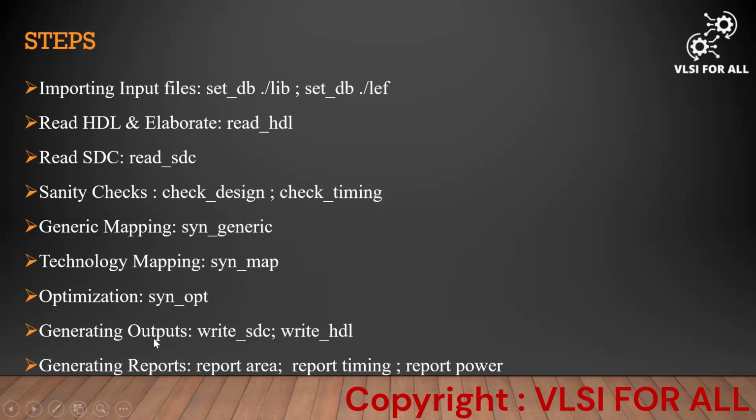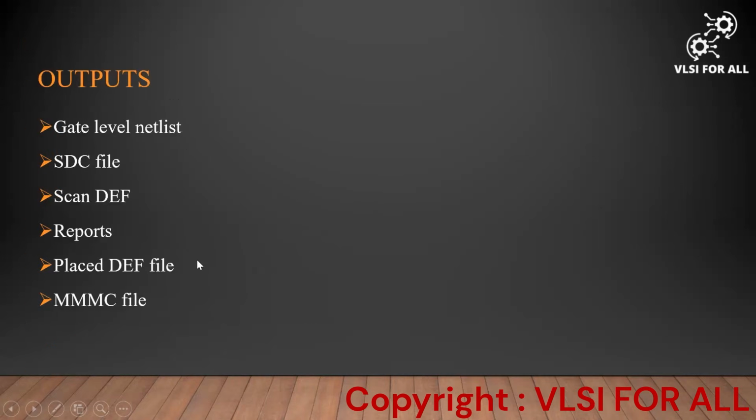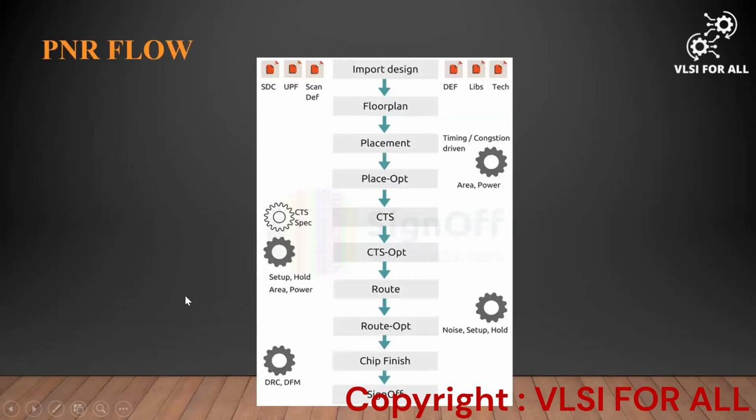Again, after that, we generate outputs. For the outputs, we have to write_sdc to dump the SDC output, as well as the Verilog netlist file with write_hdl, and also generate reports. The reports are QoR reports, report_area, report_timing, report_power. So these are all the steps in physical aware synthesis. And the outputs, as we discussed, are the gate level netlist and SDC file, scan-def, reports, placed def file, and MMMC file.